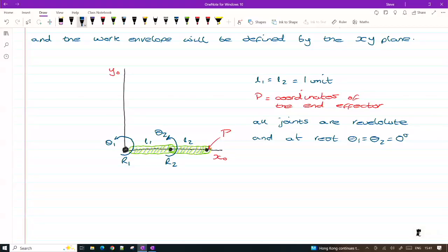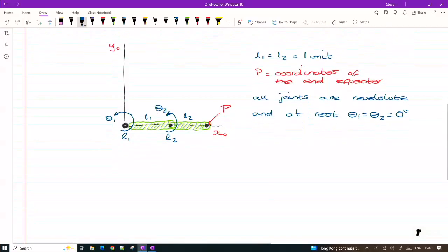That's our status at rest. Both joints are set at 0 degrees. Not always the case with a robotic system. You might have a robot whose joint has to be offset for some reason or another, so you may have to take into account that the joint, even before you start moving it, has to have adopted an angle of say 90 degrees or something, and you need to factor that out. That'll come into play a bit later on. Okay, so that's our situation at rest.